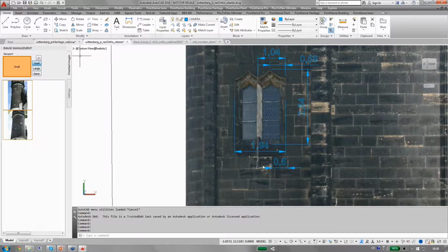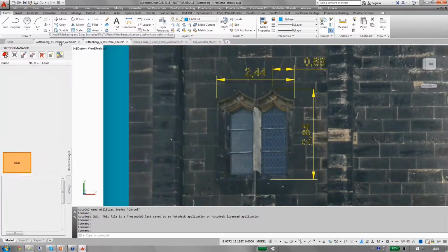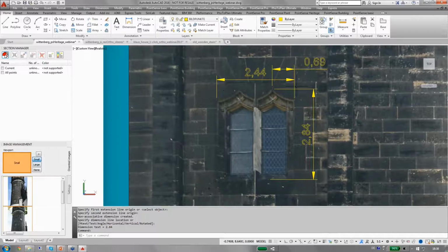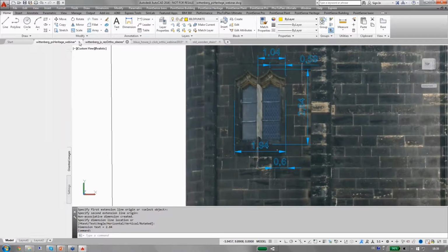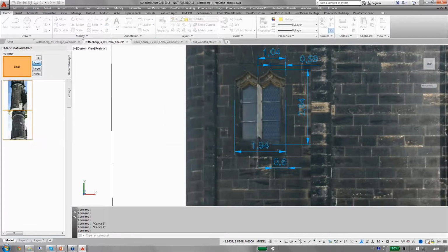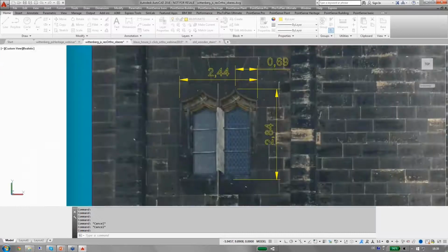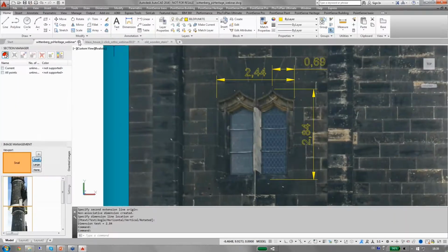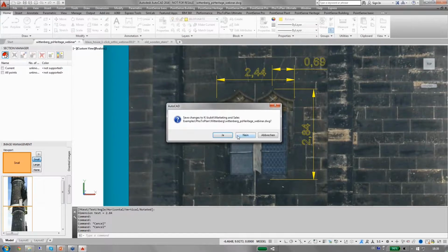When unwrapping, we have the true width of the window, which is much wider. All right. I think that gives you an impression of the difference between the unwrapping and the ortho photo. So in those cases of curved shapes, we will rather apply the unwrapping than creating ortho photos.